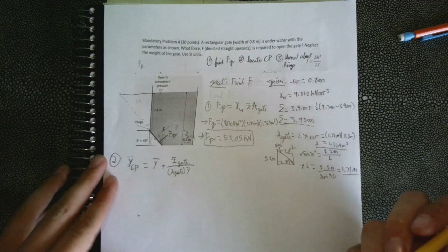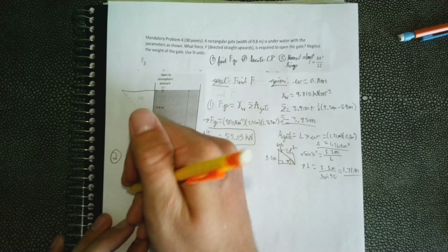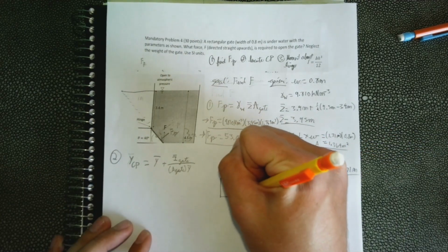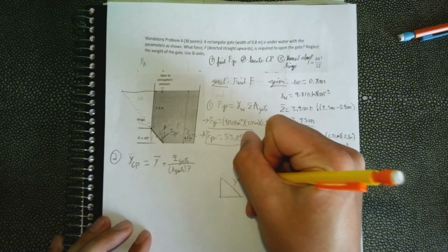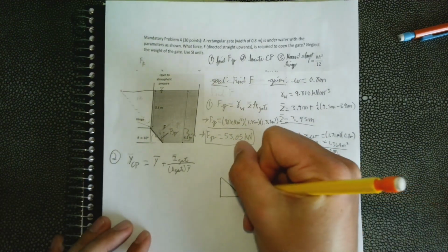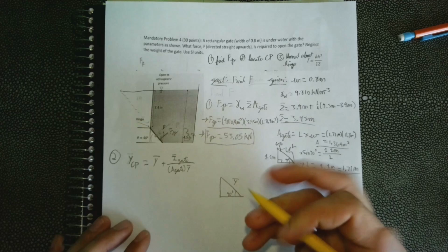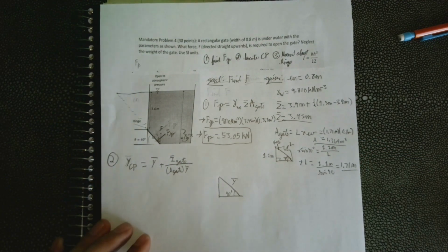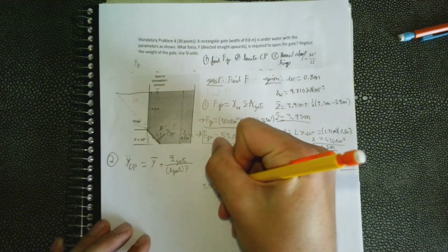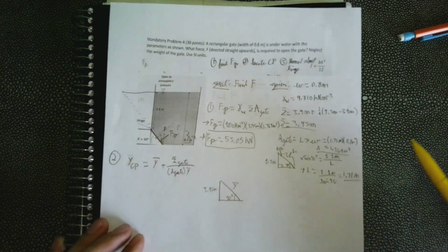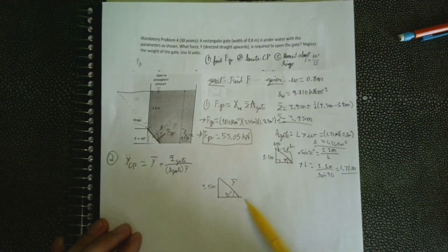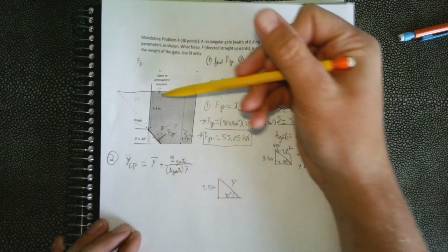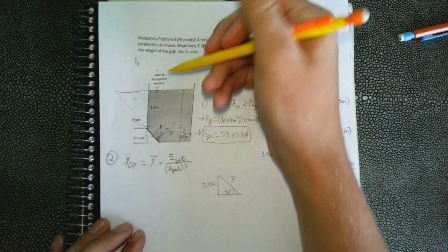To do that, we're going to have to draw a triangle again. So we got slant distance, then we got 40 degrees, right? And then we know that this value is 3.95 meters, right? 3.95 meters, that makes sense because this is the same, if you realize, as the height from the centroid, right? So if we draw this triangle,